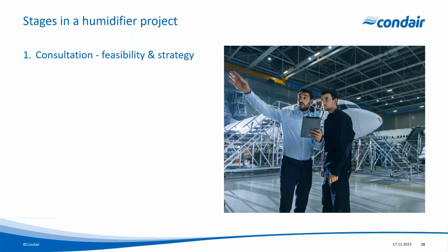We also need to look at things like services. Where's the water available? Is there a drain available? What are the power considerations that we have to think about? If we're mounting at high level, what are the maintenance issues? How is it going to be installed? Where is it going to be installed? And how can it be installed where the spray system isn't going to be obstructed by anything at high level?